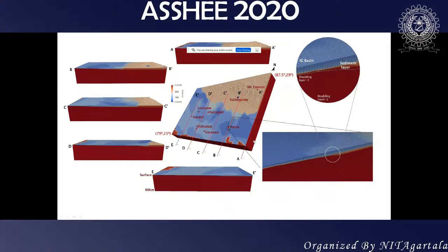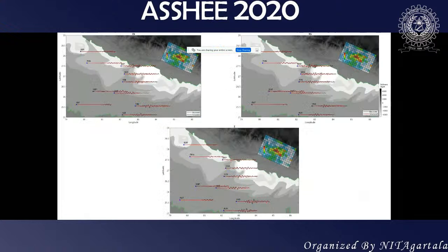By incorporating all those things, we are able to compute the soil amplification and even the basin effects, and even the effects of the Himalayan topography on the ground motion. For the Nepal earthquake, we have validated all these computational models. As I already mentioned, it was widely recorded in the Central Indo-Ganga network. You can see the black ones are the recorded ones, and these are the simulated ones. The long period waves are getting simulated in our spectral finite element method itself.